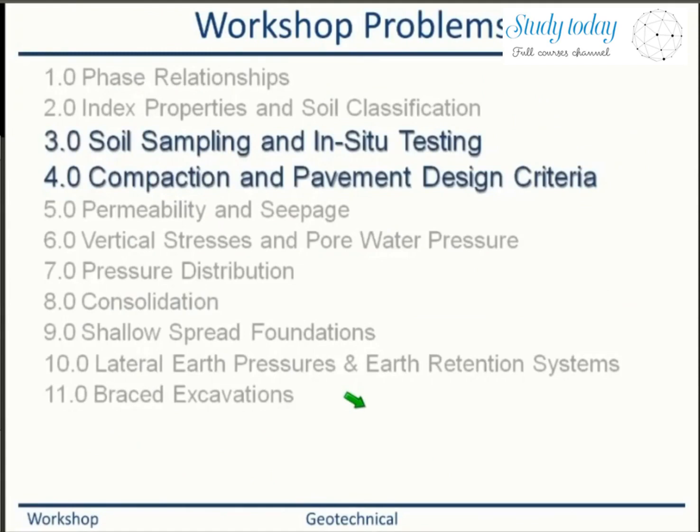Now we'll move on to, would it be tested for a residential construction, or is this more of a commercial construction? It's up to you. If your owner wants to test it, you need to test it, but you should tell them that if your investigation suggests that the clay has montmorillonite, or if you suspect it has montmorillonite, you should test it and give your geotechnical engineering report saying that this soil has montmorillonite and will swell if it comes in contact with the water. So our recommendation is to avoid building construction on this type of soil, or you need mitigation methods to do the construction on this type of soil.